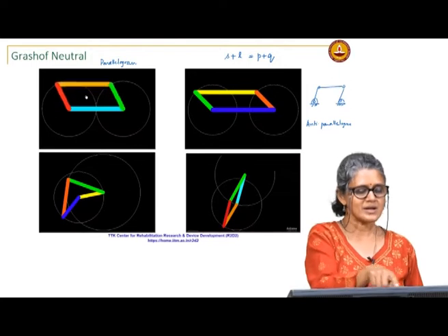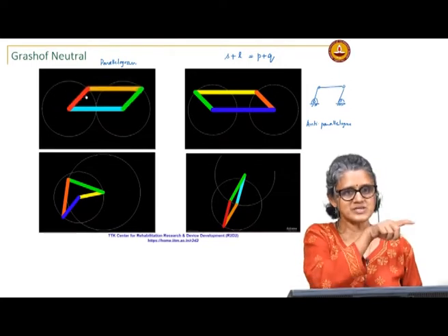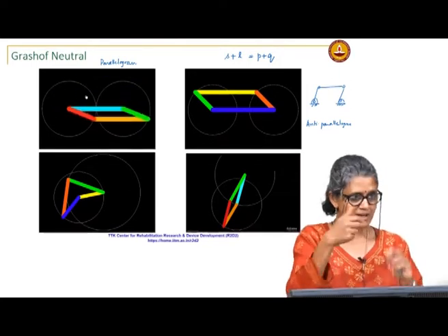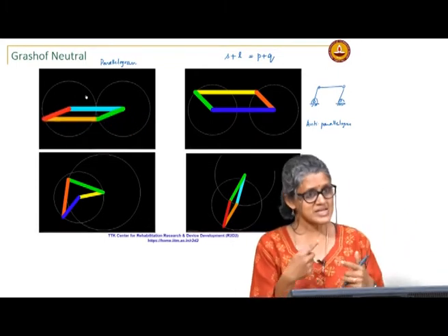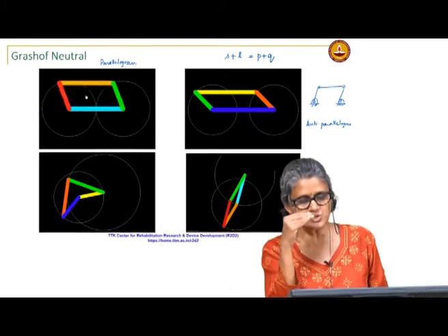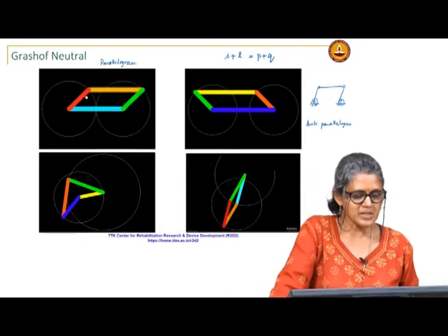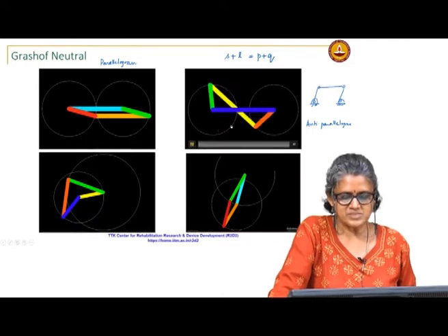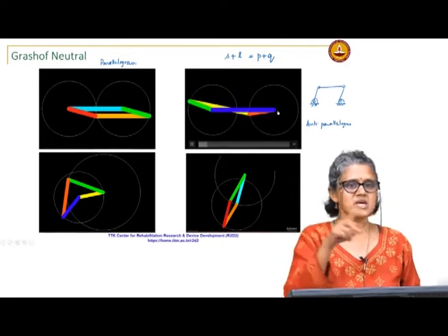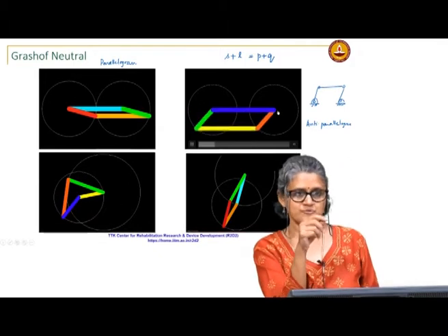So, here I think the yellow link, the mass of it is enough to carry it through and not have it switch to the anti-parallelogram form, but otherwise that is a real possibility. So, when it goes through a change point, the motion becomes unpredictable, and so parallelogram mechanisms can be troublesome if you are using them over the entire range of motion.